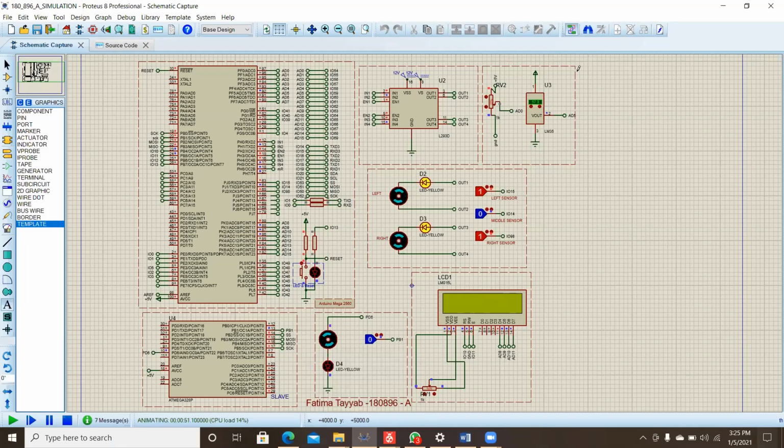It is 57 and it is 61, and when I change the resistance, the distance will change, and it detects that there is a hurdle ahead, which means the distance is less than 30. Then the motors will stop, and this shows the speed of the motor is changed with the PWM.